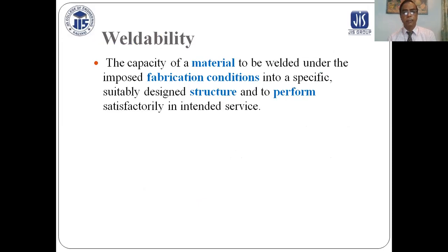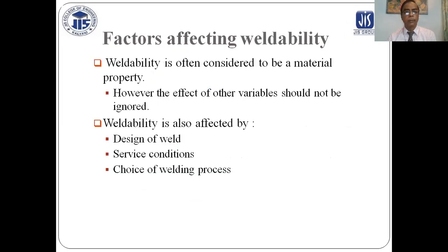Weldability: the capacity of a material to be welded under the imposed application conditions into a specific suitably designed structure and to perform satisfactorily in intended service. Factors affecting weldability: it is often considered to be a material property. However, the effect of other factors should not be ignored. Weldability is also affected by design of weld, service conditions, choice of welding processes.